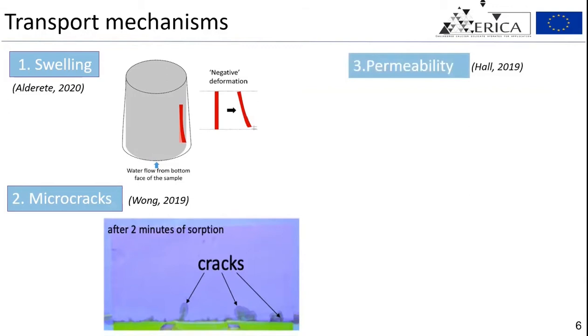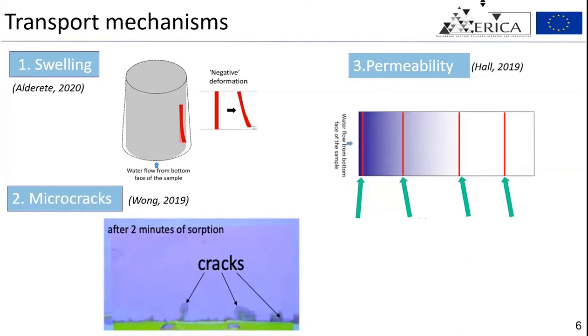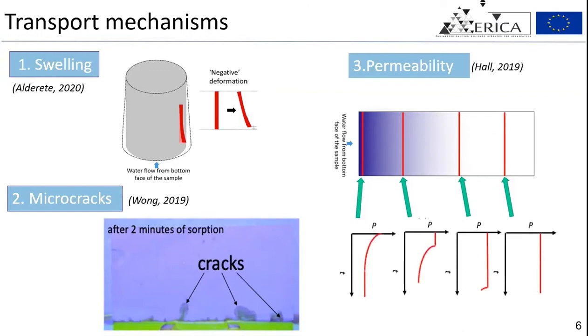The third theory is based on time-dependent permeability. The contact time describes the duration of contact between a cementitious material and a fluid source. Alteration of the permeability depends on contact with imbibed water, and therefore at any location is triggered only by the arrival of the advancing wet front. There is no one clear explanation of how water transports through cementitious materials, and in the ERICA project we use NMR techniques to conduct experiments and provide a simple diffusion and capillary-based model.